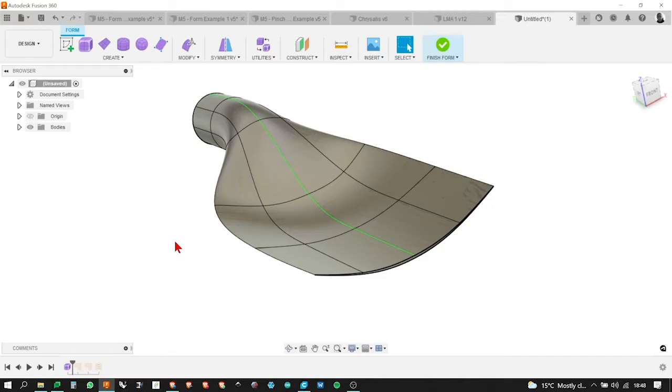So have you stitched them together? Yeah, sorry, yeah. He's done the stitch, and then it's not in with any. There's no stitch down in the icon down there. So if you go up to, oh, you come out of that sketch, you don't need to sketch. So if you go up and click on stitch, and then select the 3 bodies, you can do it from the browser as well.